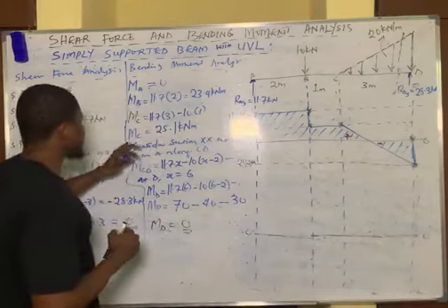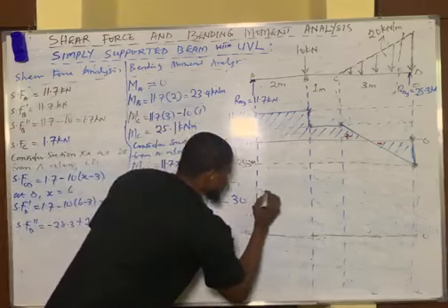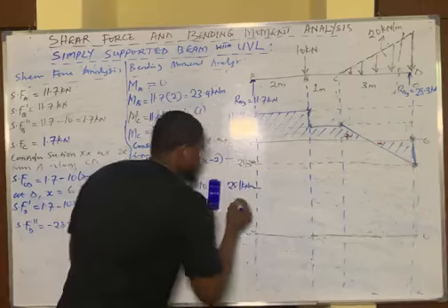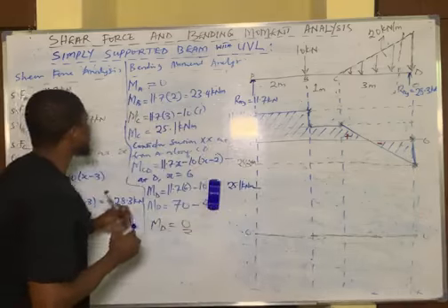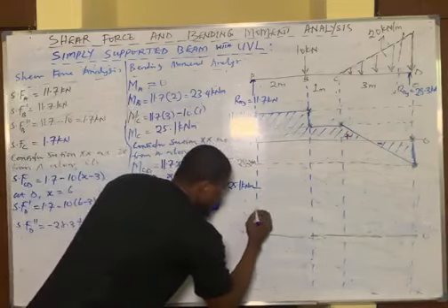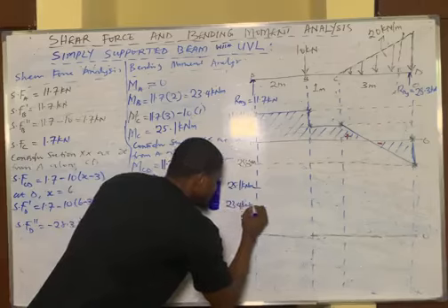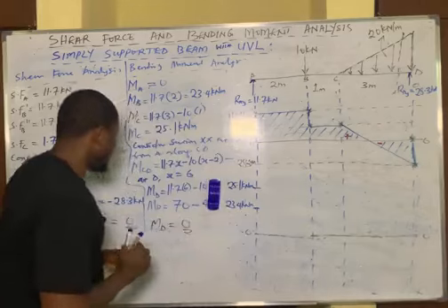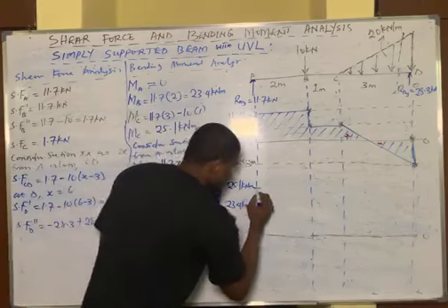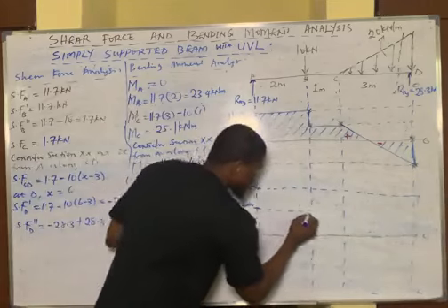Moment at C is 25.1. That's the highest. So let's keep here as 25.1 kilonewton meters. Moment at B is 23.4, so followed by 23.4 kilonewton meters. Okay, with other moments, I think the remaining is 0. Okay, so let's trace out these points.